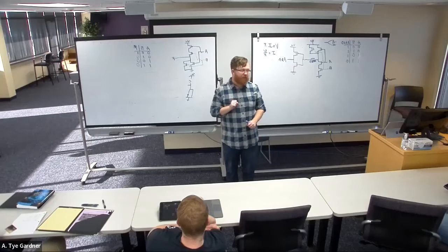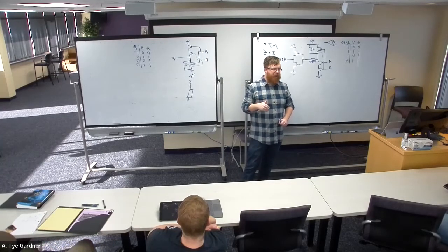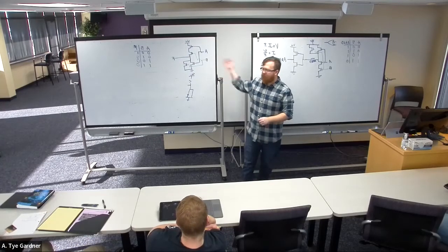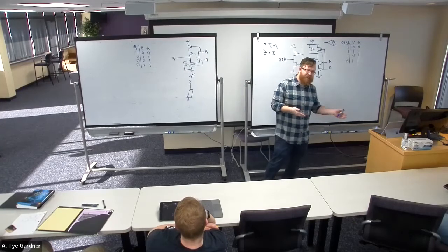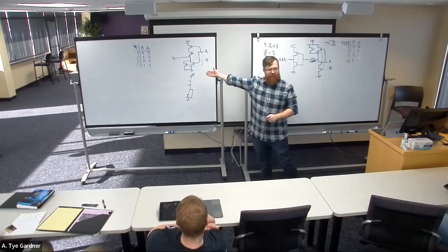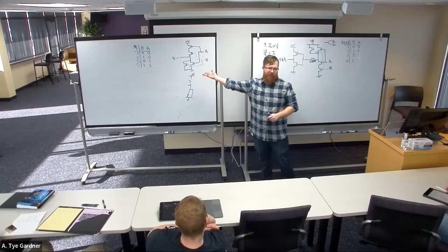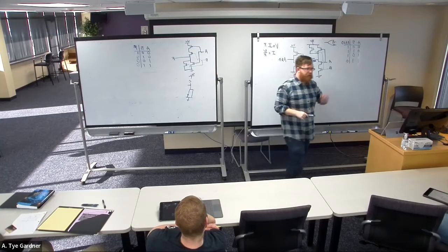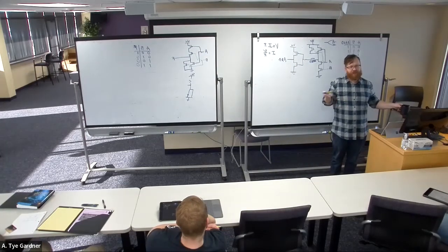If you're using AND and OR, right, you're using 6 instead of 4 for every transistor. And if you have 100 million transistors in a device and you are 50% bigger, right? 6 is 50% bigger than 4. That's a big difference. And we've already established that they're not quite ideal, which means the gates have a little bit of leakage. That also means it consumes 50% more power-ish, roughly, right? So problems. That's why we convert to NAND or NOR.